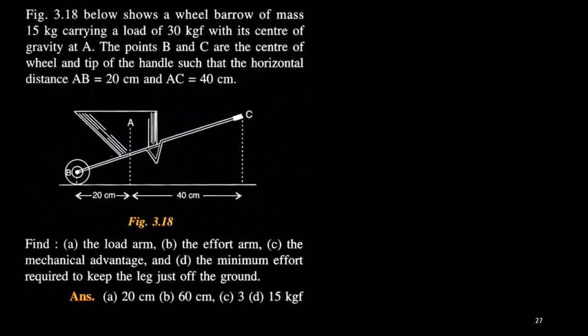Now do this. It is the position of the fulcrum, no? Here we are applying the effort. Here there is a load. So load length is 20. Effort length is 20 plus 40, 60. So mechanical advantage is load by effort.